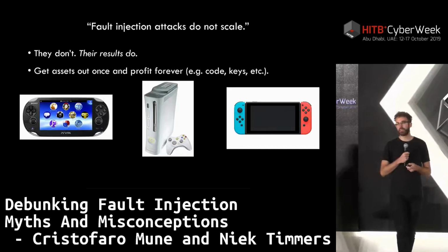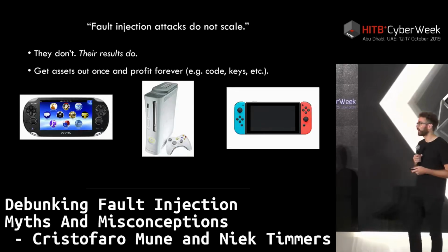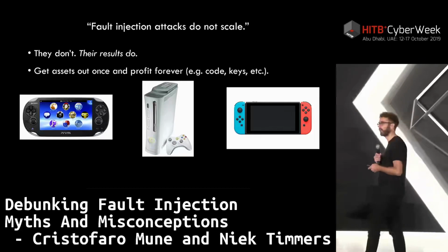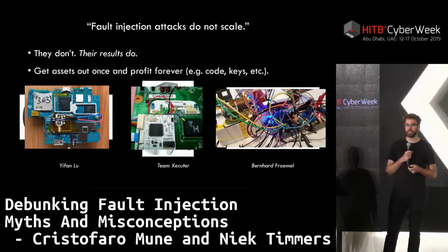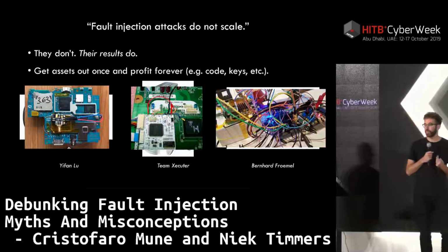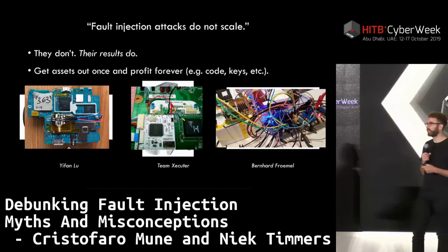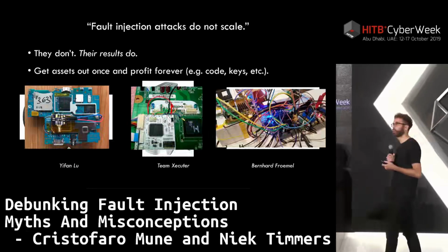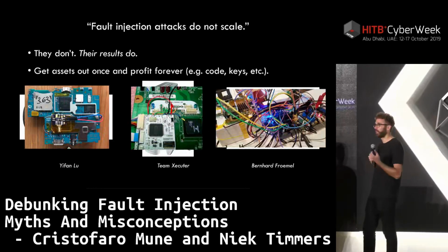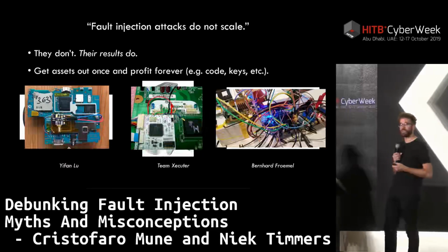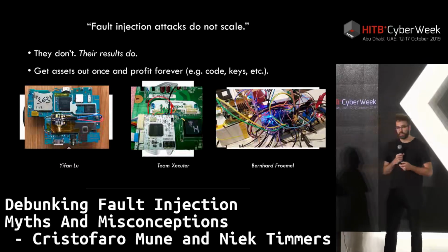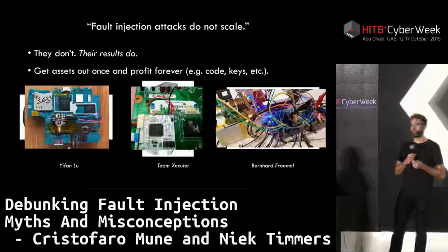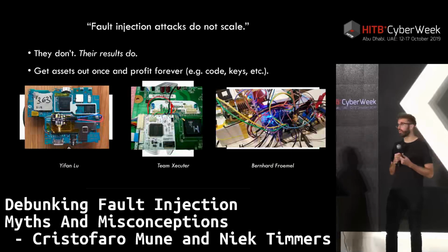So what do you think all these gaming consoles have in common, other than that they are used for playing games, obviously? They're actually all being attacked using hardware attacks. They're attacked using fault injection attacks in order to get various assets out, whether those are keys, whether those are, for example, the boot ROM, which is mapped out during boot, but by breaking into the secure boot chain at the early stage, you can recover the boot ROM and find a vulnerability and exploit it, roughly what happened on the Nintendo Switch.